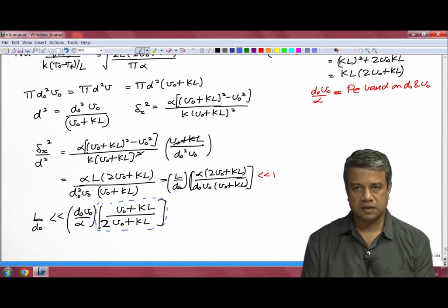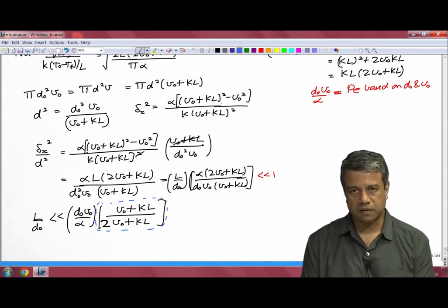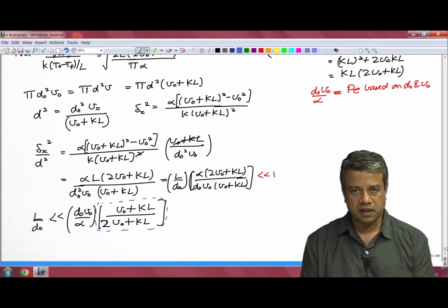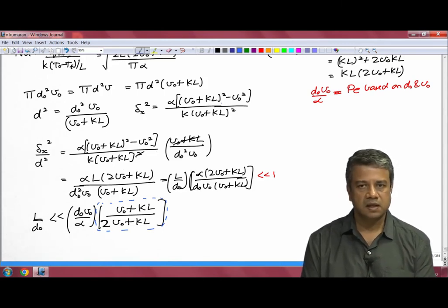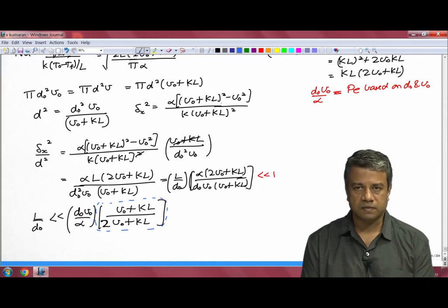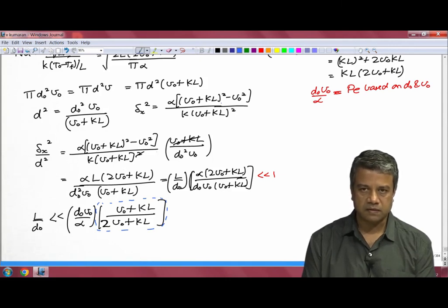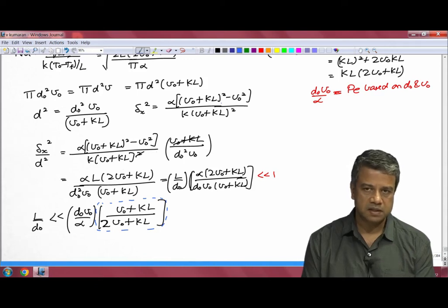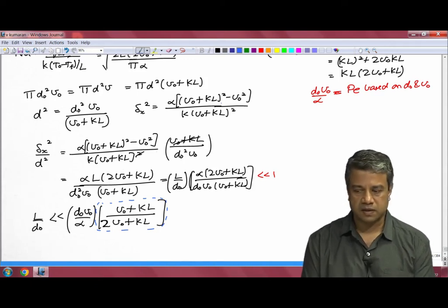We have derived general relations for a 2-dimensional flow independent of the form of the velocity profile, subject to the condition that the incompressibility condition holds. Based upon that, we get expressions for the boundary layer thickness as a function of the strain rate at the surface for rigid surfaces, and as a function of the tangential velocity at the surface for mobile surfaces. Substitute that into the expression for the heat flux, average over the extent of the domain, and divide by the total length to get an average heat flux, and from that we get the correlation for the Nusselt and the Sherwood number.